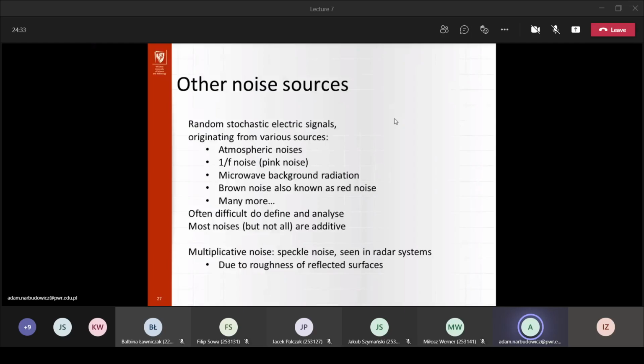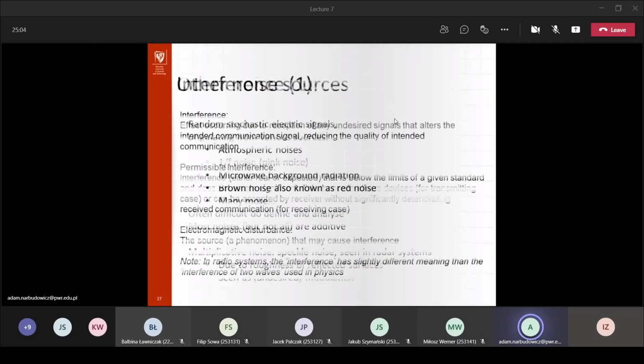The signal to noise ratio is the ratio of the signal power or signal amplitude to the average noise amplitude, right? And this can be used as a good metric to assess the quality of your signal, exactly because the noise you're assuming is additive. So if you increase your power, the SNR will also increase. Okay.